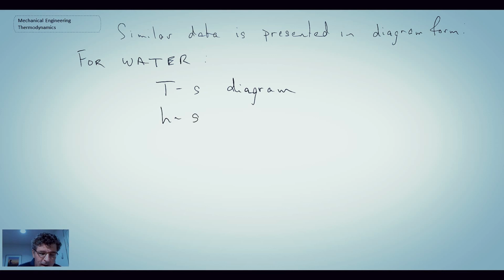And you also have an enthalpy versus entropy, and that is referred to as being the Mollier diagram. And sometimes with certain processes, you can actually go through the process fairly quickly with the Mollier diagram, especially if you're dealing with the case of constant entropy. You can just move up and down in the diagram. However, again, you have to read the charts. It's good to have a ruler if you're doing that so that you get accurate results.